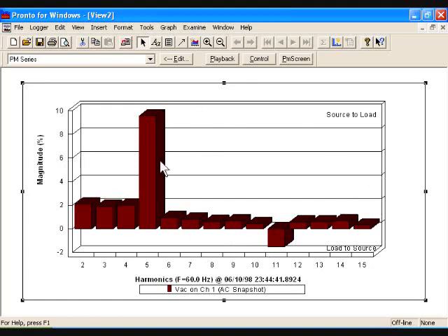And this is a very powerful tool here, because if you have a customer complaint that states, well, I'm getting a lot of harmonics, or my motor manufacturer said I'm getting a lot of harmonics, you can go up to the service coming to the building and measure and do a waveform capture. You can then see that most of the harmonics, if they're current harmonics especially, are going to be coming from the load, because most people cause their own harmonics problems. The power company typically does not generate harmonics.